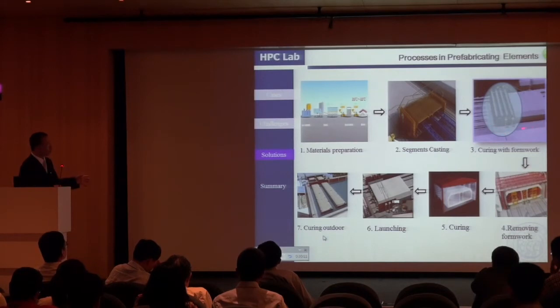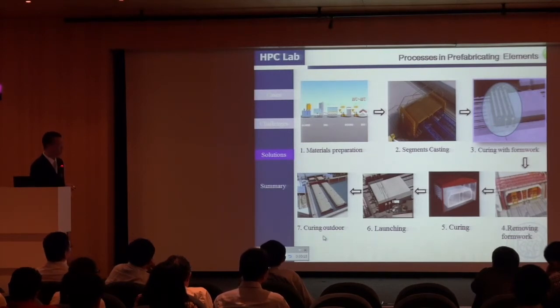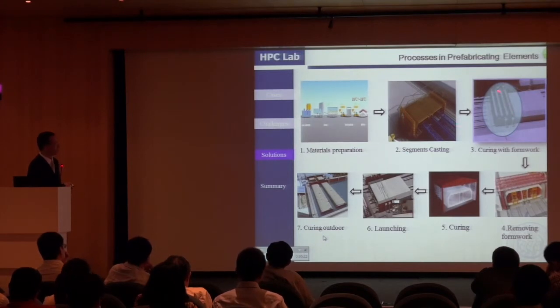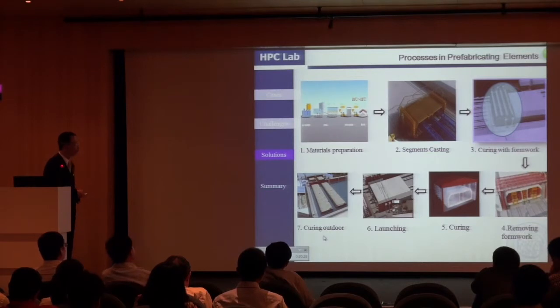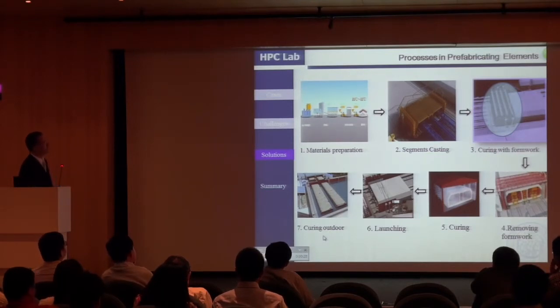For the modern concretes, there is another effect, especially during the early age, like 1 day or 3 days. So even with the formwork, it's also difficult to know what happens from the chemical reaction. We call that autogenous shrinkage. It's different from the drying shrinkage.